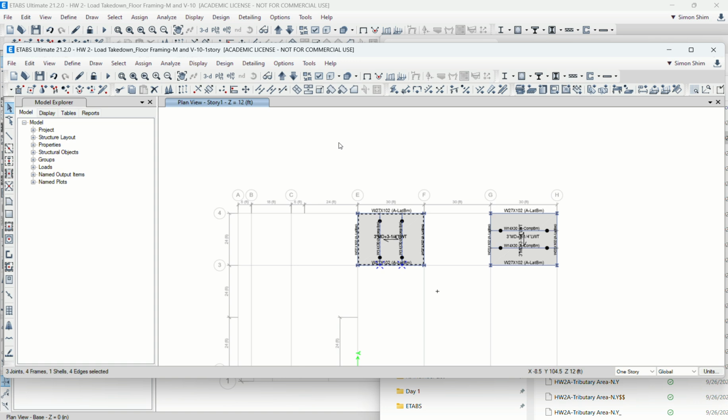The steel column and steel beam with a metal deck slab is the system we're going to use for your office building design. In general, why do we have to use a steel beam, not concrete? One basic primary reason is the span and space requirement.